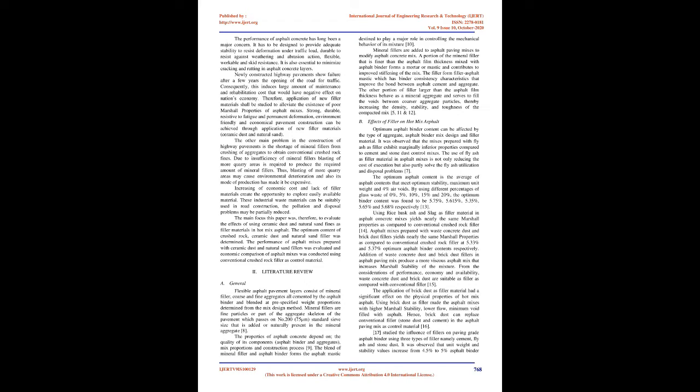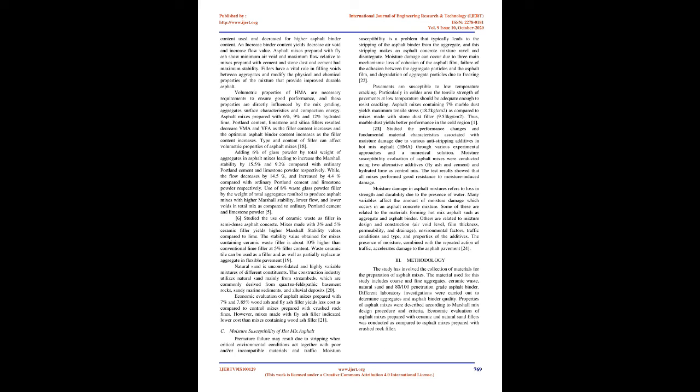The main focus of this paper was, therefore, to evaluate the effects of using ceramic dust and natural sand fines as filler materials in hot mix asphalt. The optimum content of crushed rock, ceramic dust, and natural sand filler was determined. The performance of asphalt mixes prepared with ceramic dust and natural sand fillers was evaluated. An economic comparison of asphalt mixes was conducted using conventional crushed rock filler as control material.